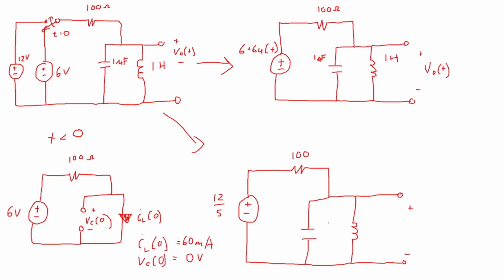So in a capacitor, we know that the source that the capacitor tries to generate is parallel with the capacitor, and the initial capacitor voltage is plus to minus. So the initial capacitor voltage source points up. In this case, it doesn't matter because the value of this is going to be C times VC, but VC is 0.